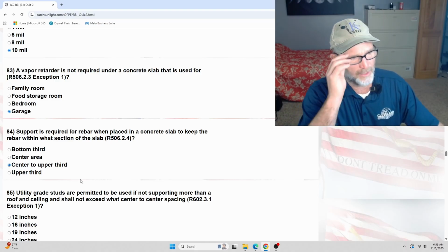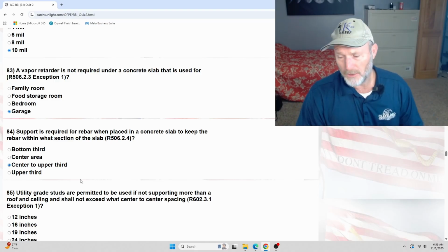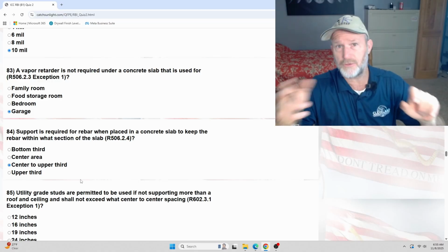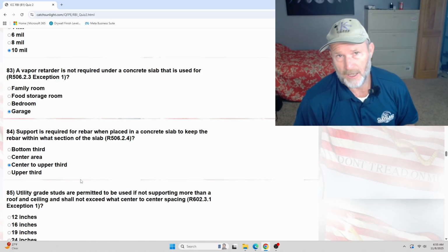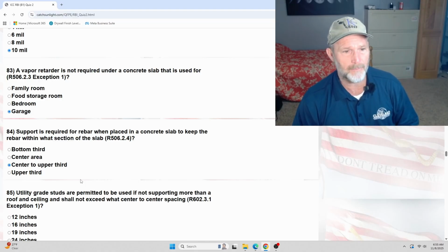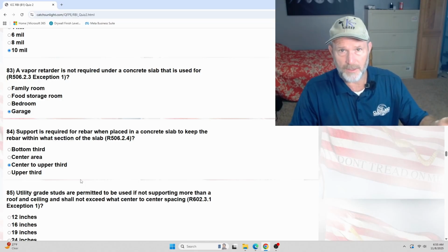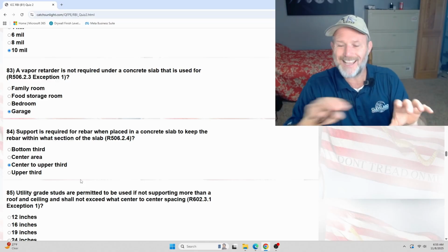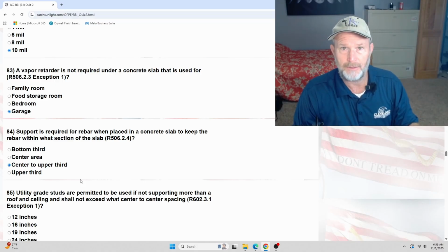And let me just explain why. If you look at a neutral axis in any beam for bending purposes, neutral is defined as right in the middle for a geometrically symmetrical beam. And we're modeling a concrete slab as a beam. The neutral axis, right in the middle, technically doesn't bend.